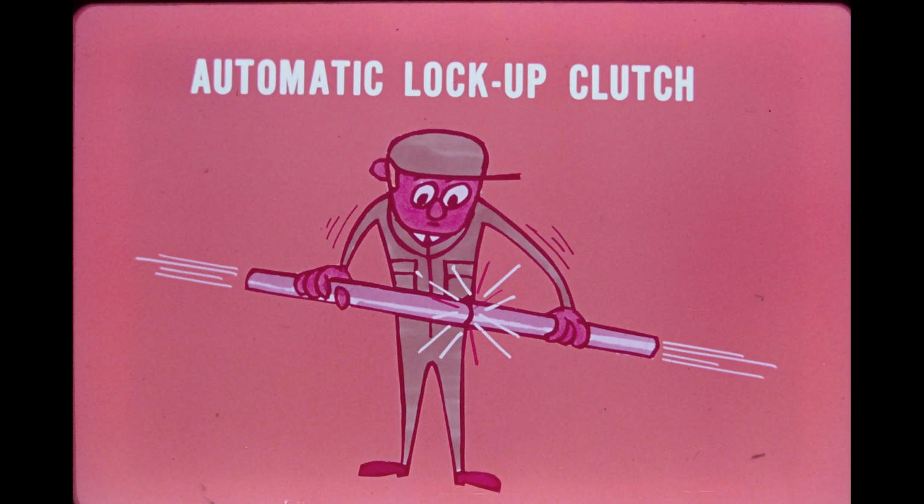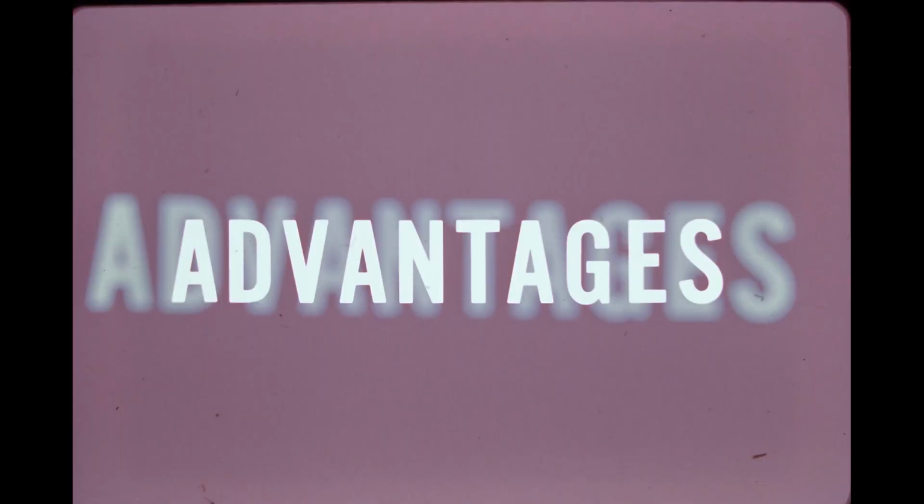For example, consider the varying torque and speed requirements of an elevating scraper. When the scraper is in the cut, a great amount of torque is required to keep the machine moving to load the bowl. However, once out of the cut and onto a well-maintained haul road, the torque requirement falls off and speed becomes important. And to get the high speed required, the mechanical lockup engages and provides optimum drivetrain efficiency for faster cycle times. Drivetrain efficiency and faster cycle times are certainly two advantages provided by the torque converter.